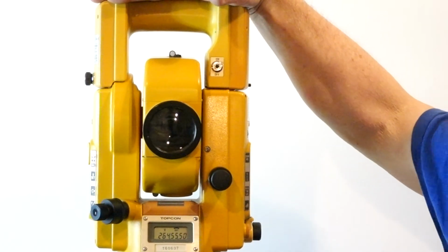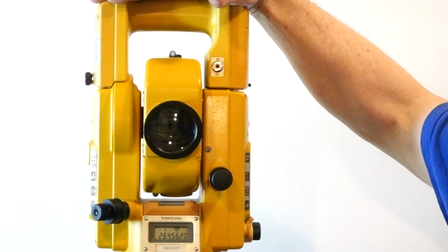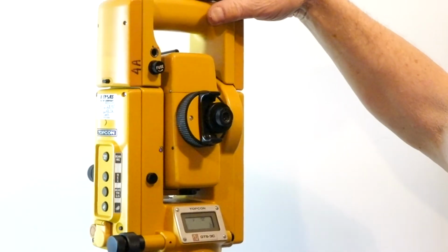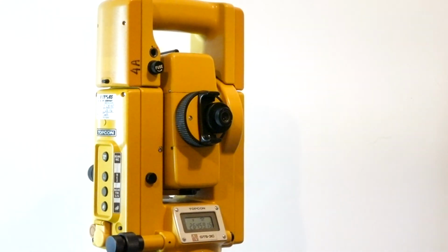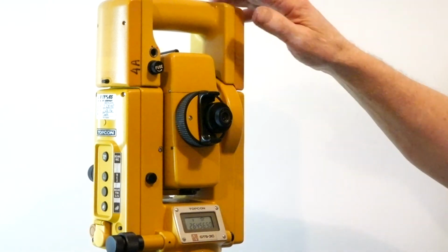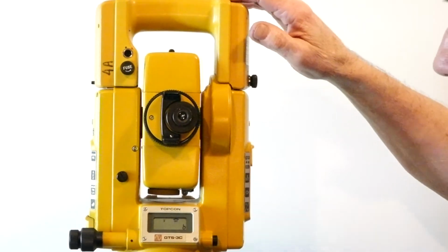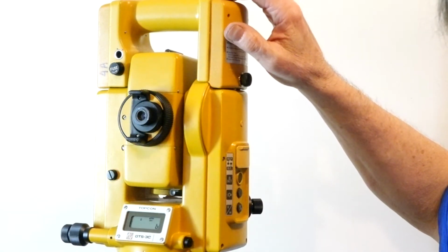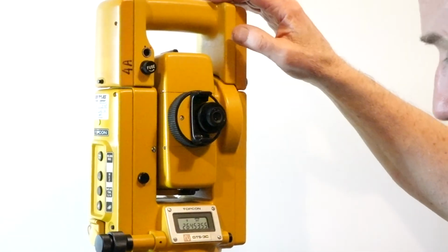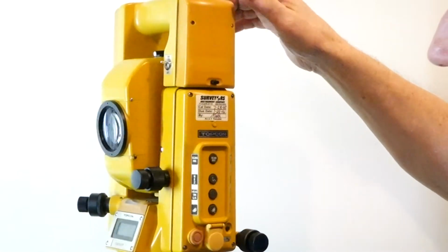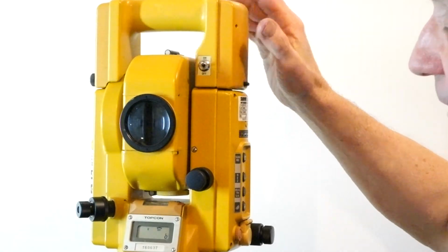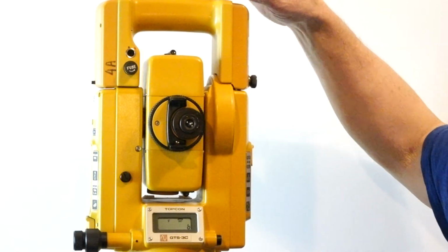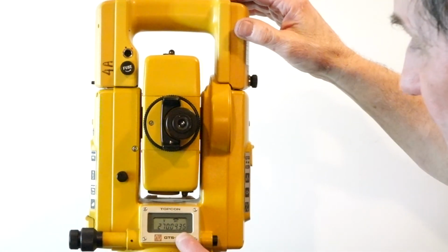This is a secondary piece of equipment that I'll be using. This is called a surveyor's total station. This is a Topcon GTS-3C. It has an accuracy of 4 arc seconds, or 4 seconds of an arc. It can measure vertical angles, horizontal angles to that precision, as well as distances. There's an infrared laser inside here that's used for making the distance measurements.